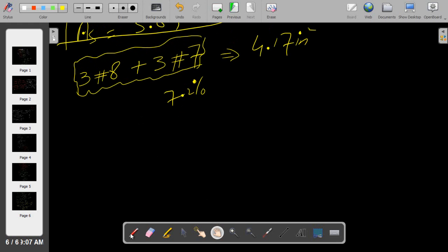We will find the B minimum, or spacing between bars, which is also a check on whether we can adjust these 3 number 8 bars in one layer or in two layers.